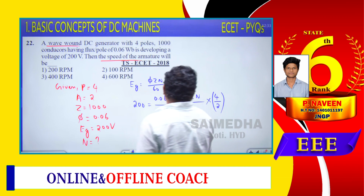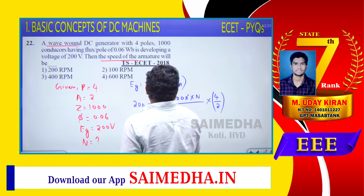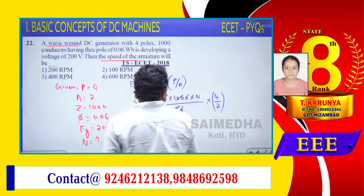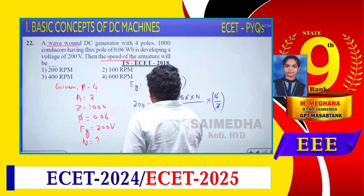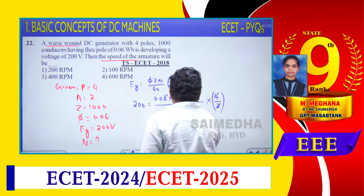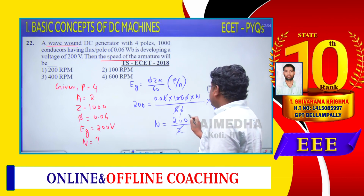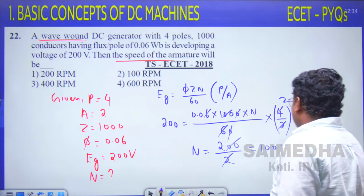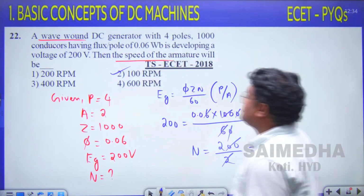So the 60 will be cancelled, the zeros will cancel, and also the 6 and the 6 will be cancelled out. Now it is equal to 2, so N is equal to 200 divided by 2. So this is 2 times N equal to 200, so N is 100 rpm. So option 2 is correct for this question.